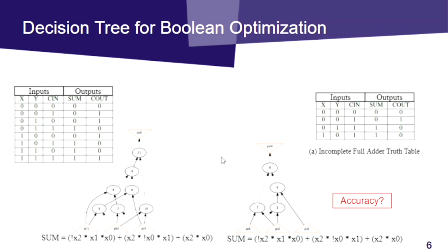To demonstrate how to learn from an incomplete Boolean equation, we can assume a randomly defined incomplete truth table with half of the full adder's minterms. This reduces the table used to train a decision tree. The training set has then 4 minterms for training, and the other half of the complete table is used as the validation set. The learned expression and AIGs obtained had a reduction on the number of nodes and literals in the expression. However, as you can imagine, it will impact the accuracy of the solution, giving us approximate circuits.